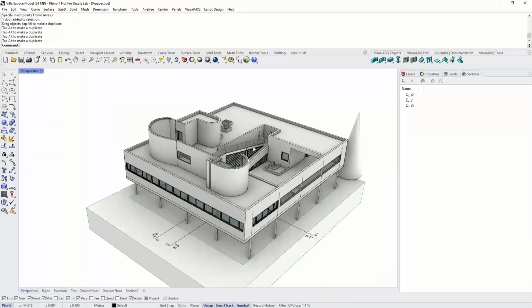So let's take a look at the way to create new styles. For example, here, if I right click, I will open the styles dialog of the wall object, where we can see the existing styles. If we expand any of these styles, we can see the number of layers. Selecting them, we can change their features. We can assign a material, we can assign the section attributes. In this case, of course, it will change the whole style. Or we can edit other details like the thickness, construction.